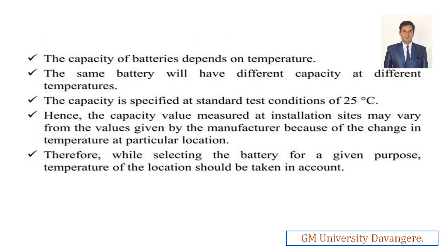Next, the capacity of the batteries depends on the temperature. As I discussed regarding the state of charge of the batteries, when the battery starts charging and starts discharging, during that instant the battery temperature may rise and lead to degradation of the battery life, and the C rate also. Right. The capacity of the batteries is a very important factor if you consider the temperature, right?